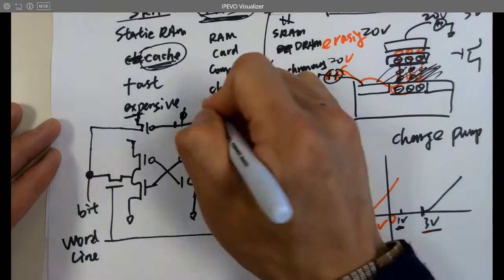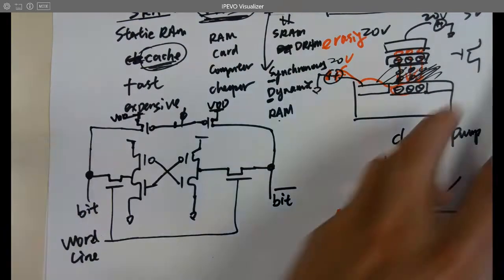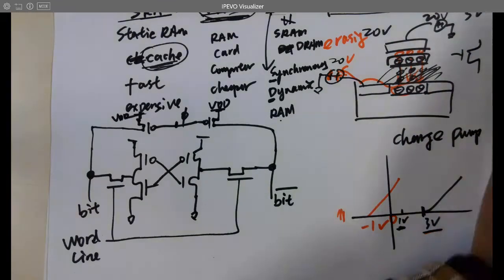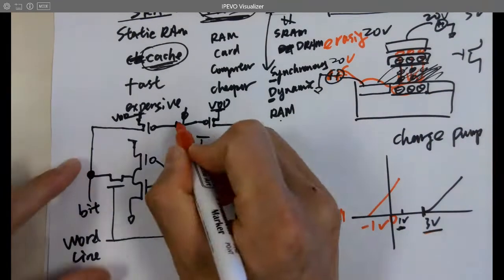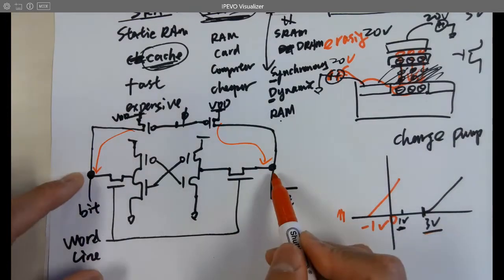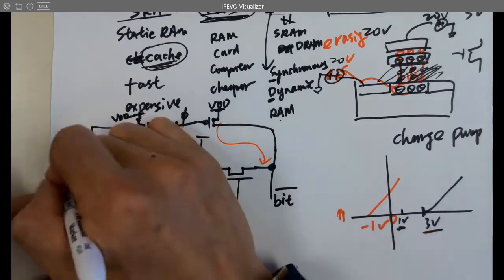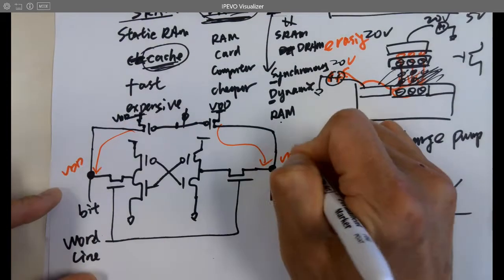So these are PMOSs that are connected to VDDs, right? So whenever you turn it on, what's gonna happen? You turn that gate on, turn this on. So current is gonna flow through and charge this up, right? Charge the 2 points up, okay? And then you turn it off. So they are getting a floating VDD here. Floating VDD.